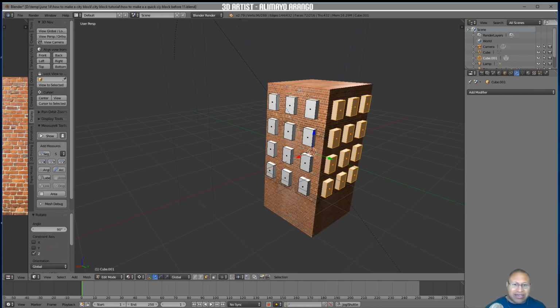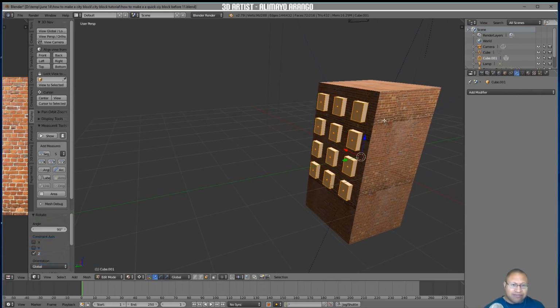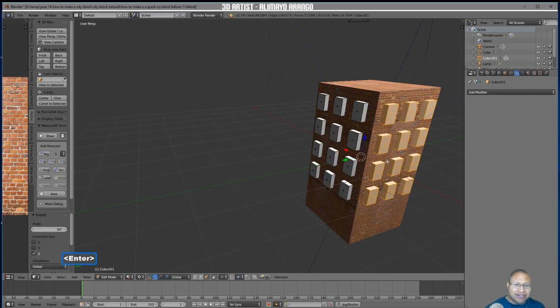By the way, if you need your 3D cursor to be perfectly centered in the middle of your building for this to work, if you got your 3D cursor off center, you can press Shift C, and your 3D cursor will be right in the center of your scene. So hopefully your turning went okay for you. So we have one more group of cubes to do. With these selected, we're going to hold Shift, press D, right click, and then press R to rotate on the Z axis 90, and then press enter to lock that in.